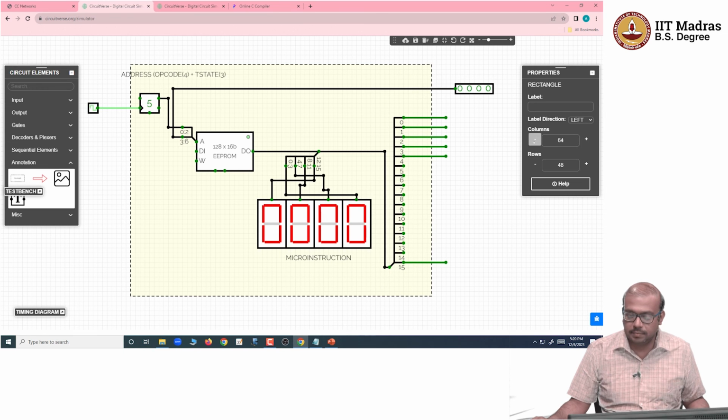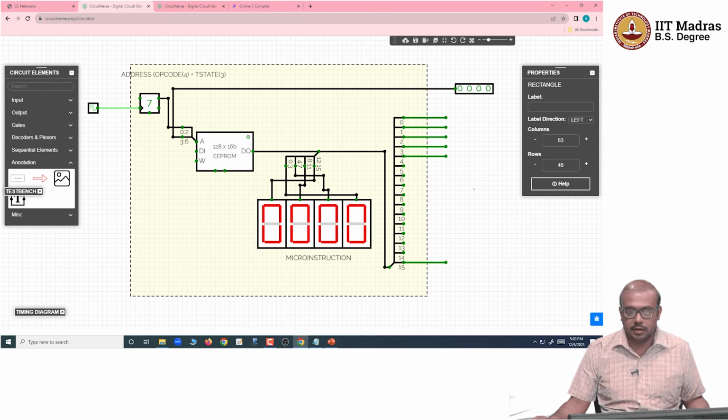This entire thing becomes the control logic. This is an input coming from the processor to the control board, as you can see. This is going to come from the instruction register. This 0000 depends on what your instruction is. It is going to come from the instruction register, and the instruction register is these 4 bits only, right? Not the data, not the address. The most significant 4 bits of the instruction is going to be the opcode.